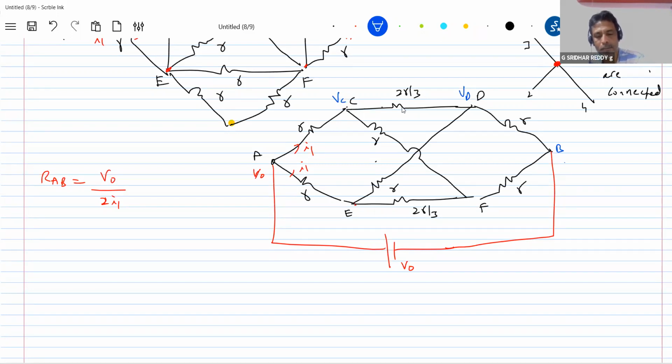Okay, this one. So what was the rule we made? If any resistor is directly connected across equipotential points, remove it. Again, we didn't say that after removing, make them a common point. I think that will be a very bad idea. No book has suggested that, as far as I have come across. Maybe you end up with the answer, but it will not work in all cases.